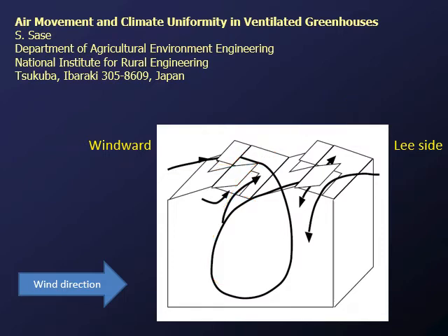There's a couple of reasons for that. One of them is also that if you have a strong wind coming and you have your vent, so here's my greenhouse, right? And I've got my vent sticking like this and like this and like this and like this. The wind will actually hit the vent and knock the glass off and send it flying and smashing. So we try to limit the vents that face the wind so that they don't open as much as the vents that face away from the wind.